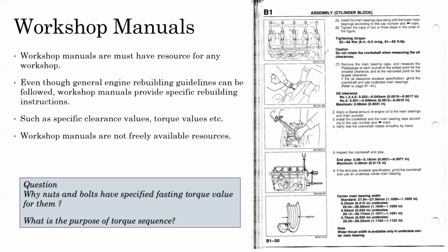That's a lot. So it's not 0.8 inches. If I am correct, it should be 0.35 millimeters and 0.3 or 0.25 millimeters, something like that for intake. That's the usual values, but they are not the exact values. 0.8, 0.6 clearance is not for